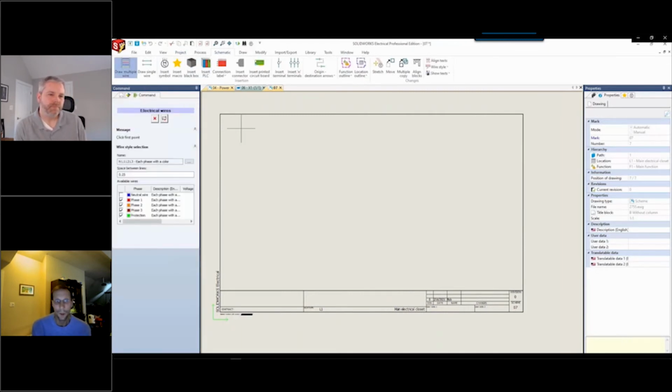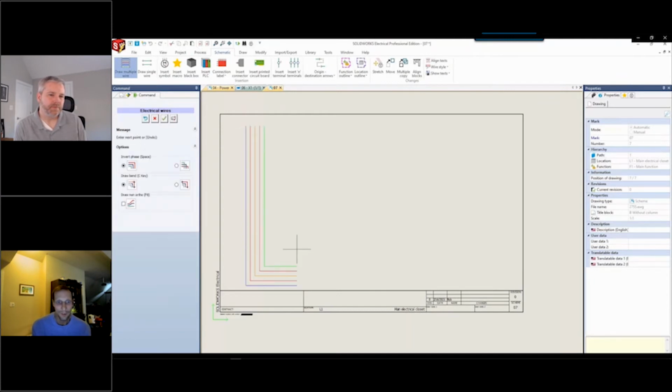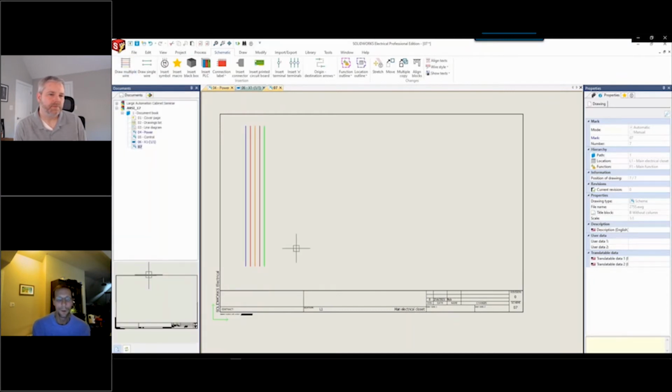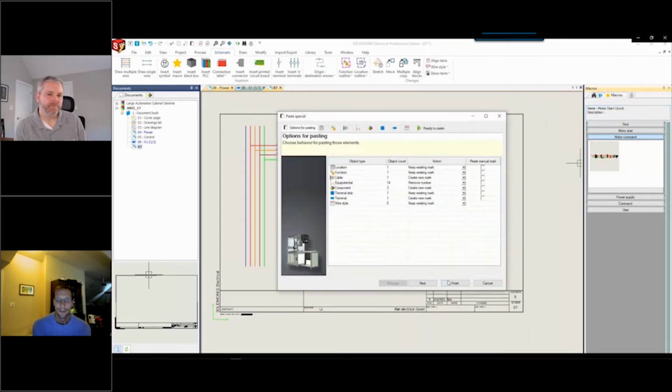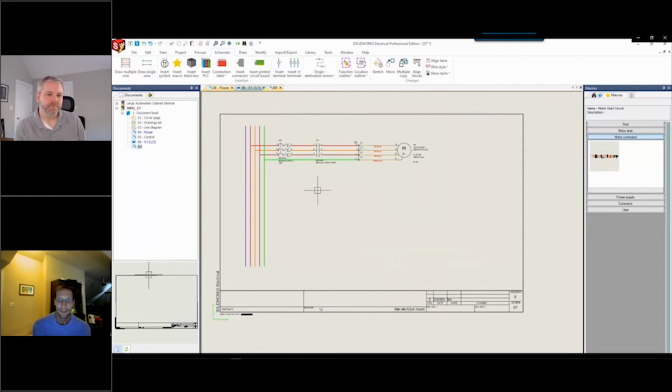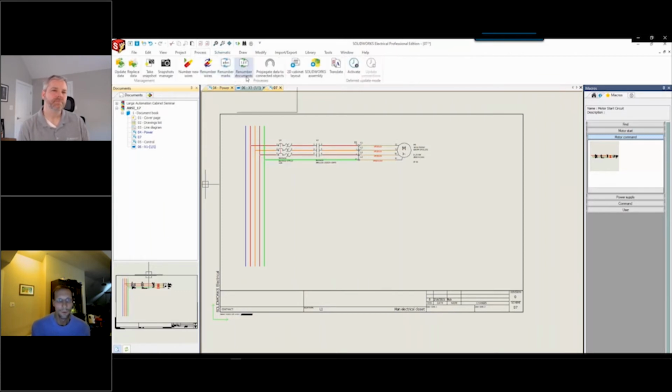I'm going to continue working on that circuit, just creating a new page. I have some more work to do, right, as we usually do, so I just create a new page, and we'll get that same wire scheme out on there and drag that same macro back onto my page, connect it in, accept my indexing, and now have my other motor in. I'm going to go ahead and rearrange that tree because, as in real life, things don't happen in a logical order. We have to make audibles happen every day. So just know this works with you. It's very fluent and flexible.